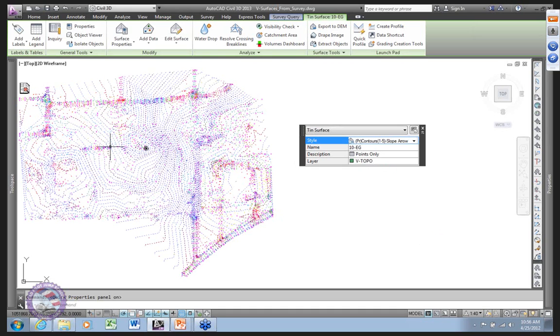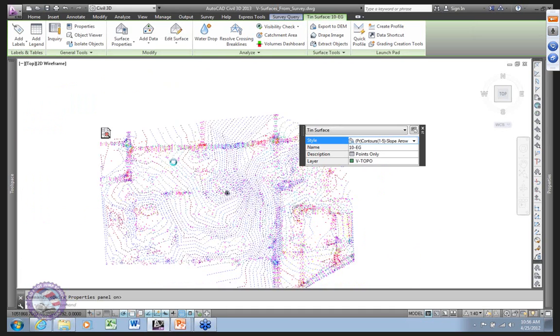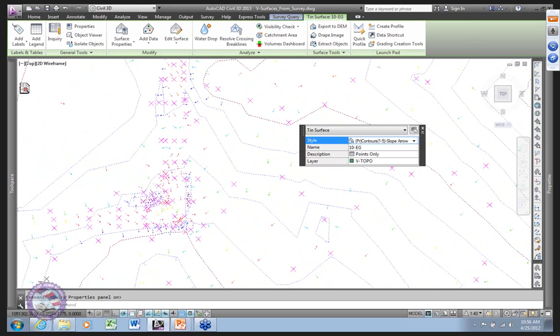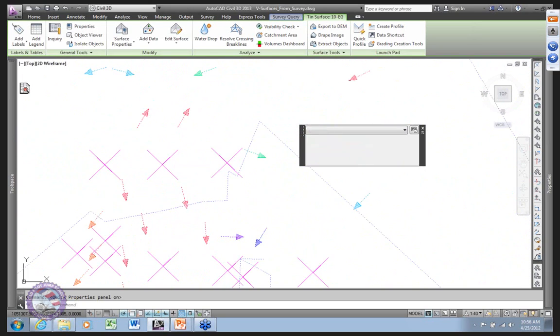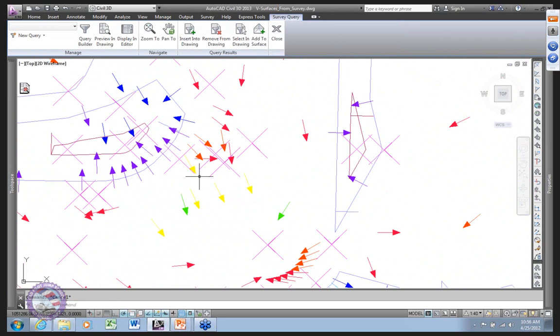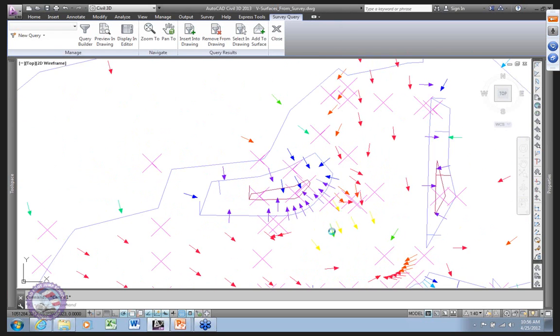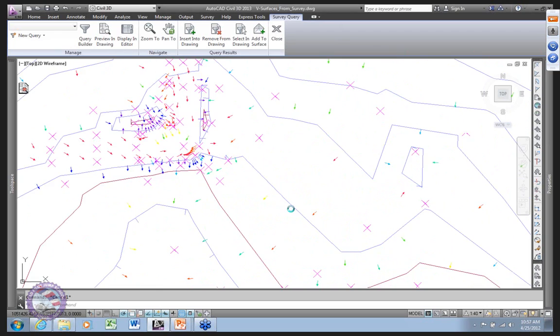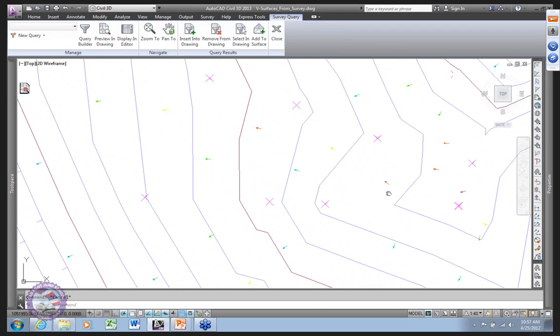Okay. And we're going to zoom in here. My little arrows link will actually show me where I got break lines. You'll see I do not have, I just have back of curb. So anything that's darker or bluer effectively is steeper, okay, in this style. The way it's currently run, just the default 8-inch analysis.